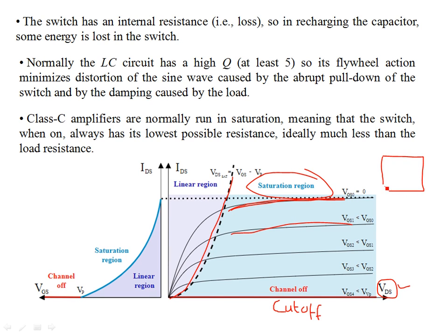Okay, so it's something like this over here. For example, if this is a P-type region, this is an N-channel JFET. This is a P-type region over here. There's another P-type region over here. Okay, and this is an N-channel. It's P-type, and let's say the channel is N-type. There are electrons over here, and you have a drain like this. This is my drain terminal, and then I have my source terminal over here. Okay, so we are going to connect these two terminals, let's say through a battery. There is a battery, the positive terminal is the drain, the negative terminal is the source.